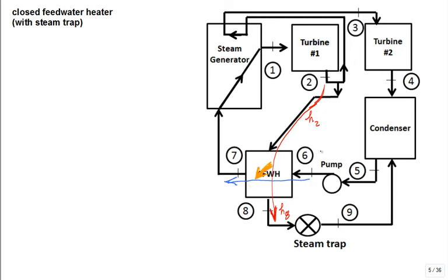Okay, now this steam right in here may be some very high quality, high pressure steam. Maybe the quality at 2 was, I don't know, 97%. True? So what you can do is, if it's coming out at the same pressure, the pressure at 8 equal to the pressure at 2, there's no pressure change in that fluid stream. There's no pump or turbine, so we're going to neglect the pressure change. Yes, in the real system there's a small pressure drop, but here we're going to neglect that pressure change. What is the condition of the fluid coming out at 8? That would make sense.